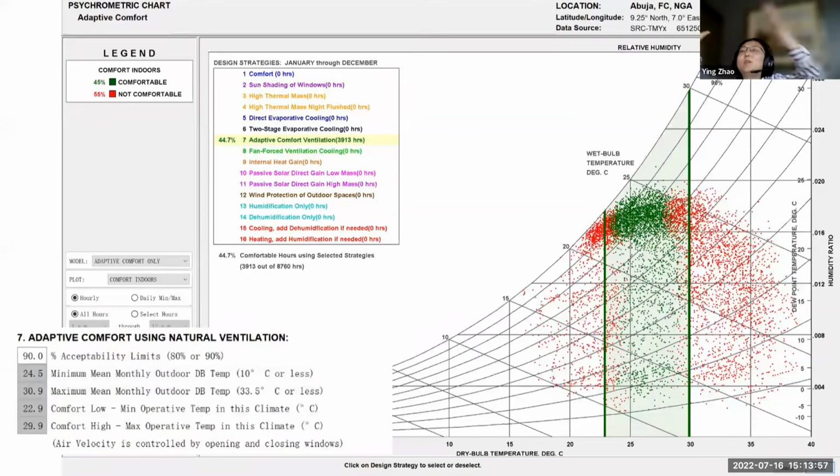But if you have a building that has a lot of inside space, that will be different. If a building is really huge, with a lot of inside space, this analysis will only be applicable for your perimeter zones, but not your internal zones. In a very big multiple floor building, the internal zones don't have heat exchange with the outside of the building, so cooling will dominate the inside of the building. So this analysis will not be applicable.